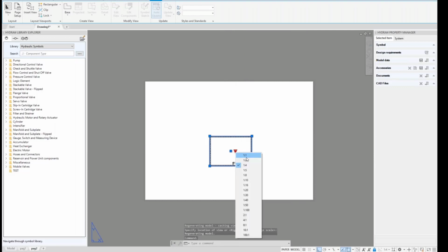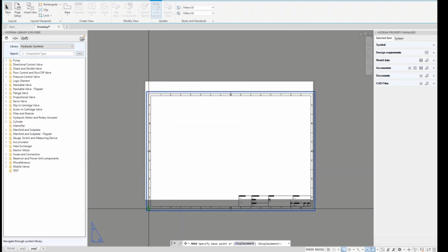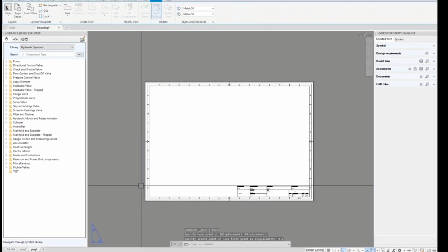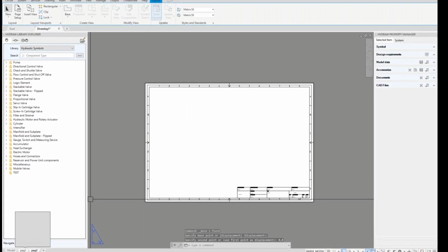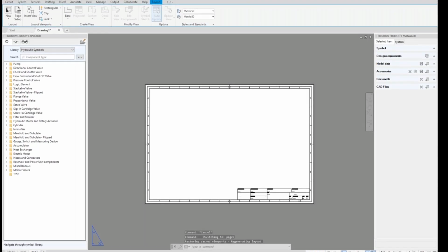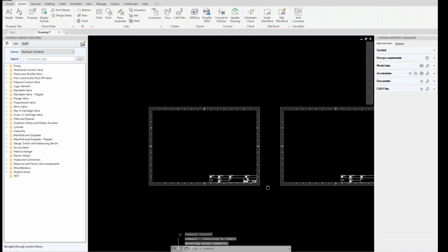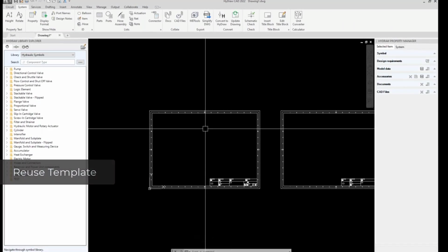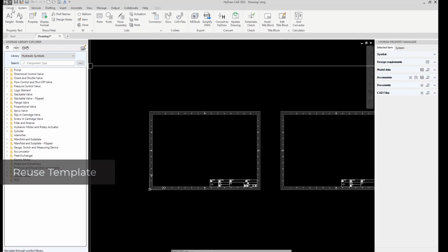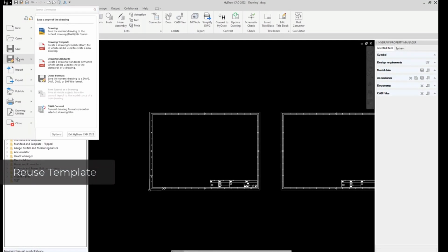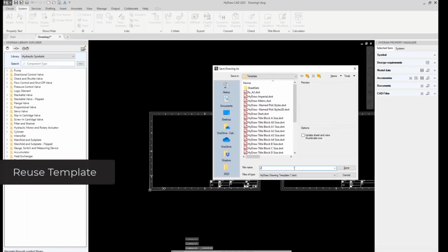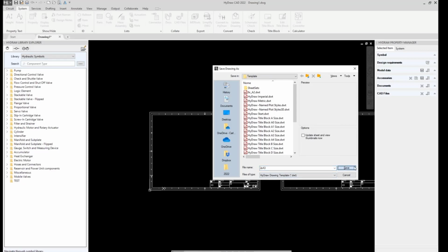The scaling will be 1 by 1, and again I can move wherever I want. 0, 0, so it goes directly to the origin. So now that I have prepared my document, page 1 and page 2, and in the model space, I have everything ready to start. Of course, if I want to reuse this in the future, I can just do file, save as, drawing template, and here I could save it as 2 pages A3. So then next time I can start from here.